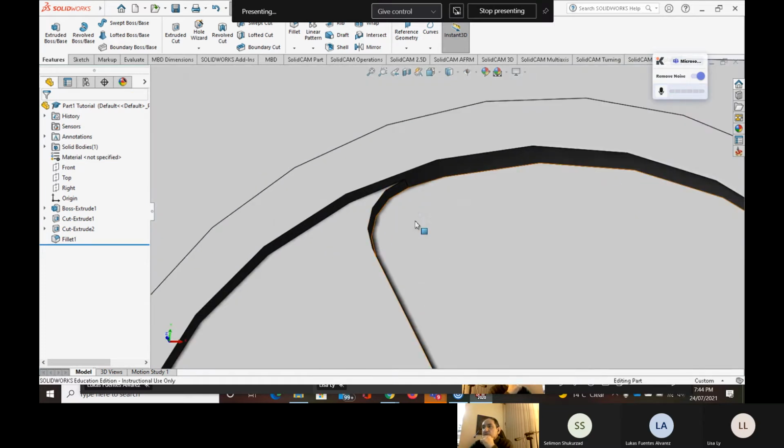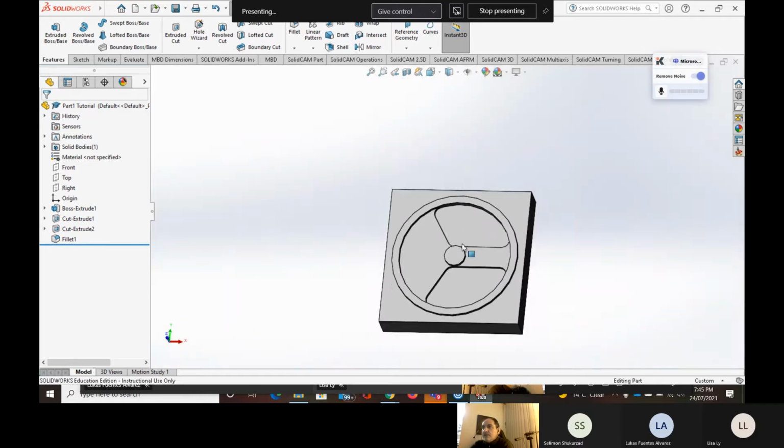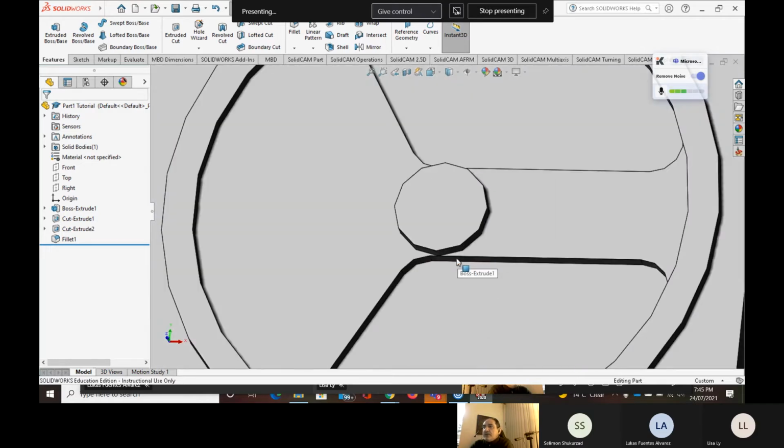That means the cutting tool will move along this line, stop here, then change direction. So the center of the cutting tool, of course, is going to be offset by the value of the radius of the cutting tool. Now, what I'm going to add is a hole here with 10 millimeter diameter and 10 millimeter depth, and another hole here with 10 millimeter diameter and 2 millimeter depth.